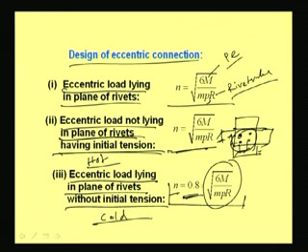So, on this basis we can find out whether it is a power driven hot rivet or a power driven cold rivet. If it is a hot rivet, then we can assume that initial tension is there, and if it is a cold rivet, then we can neglect the initial tension and accordingly we can make it. So, in case of cold rivet the number of rivets will be a little bit less. So, with all this we can make the design accordingly.